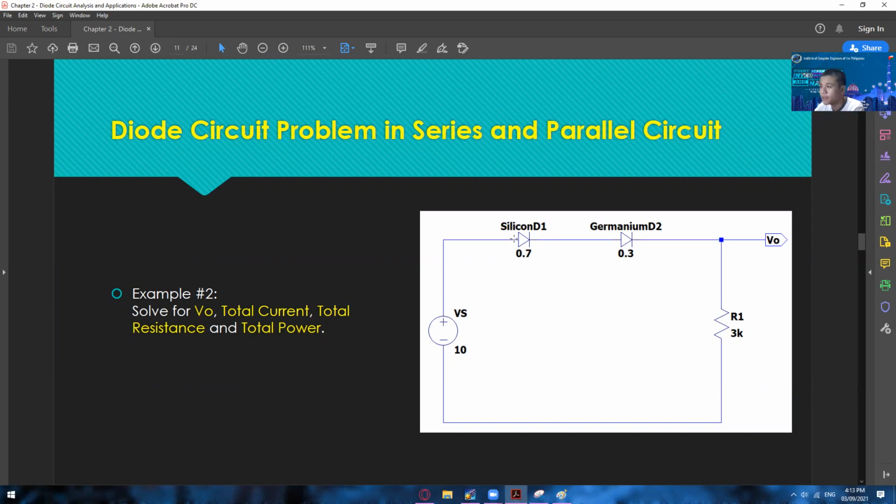In here we have a series connection of a silicon diode and then a germanium diode. This one is D1 and then D2, so we have a total of two diodes in this circuit. We have a voltage source of 10 volts, and a resistance of 3 kilo ohm. In some cases I don't usually put 0.7 here, but just to remind everyone, since this is just an example, a silicon diode will always consume 0.7 volts.